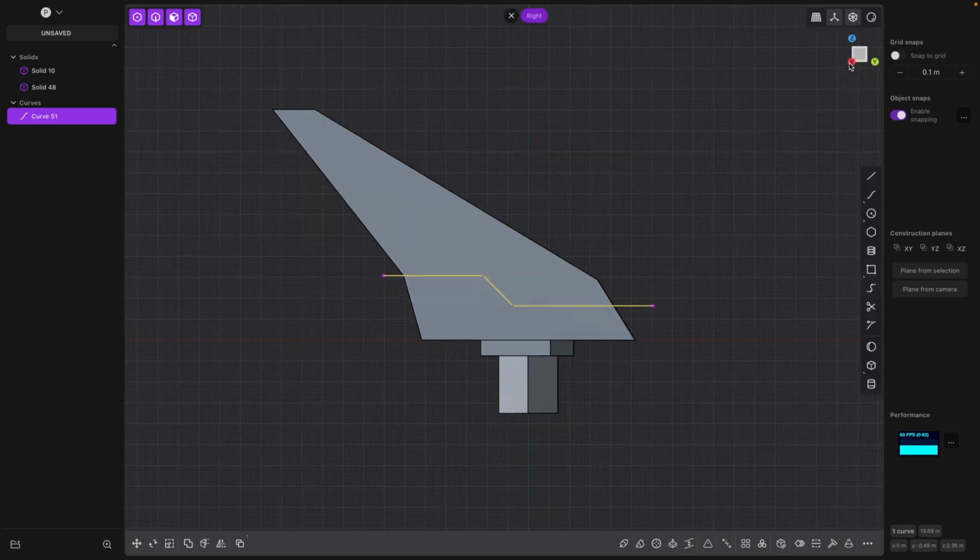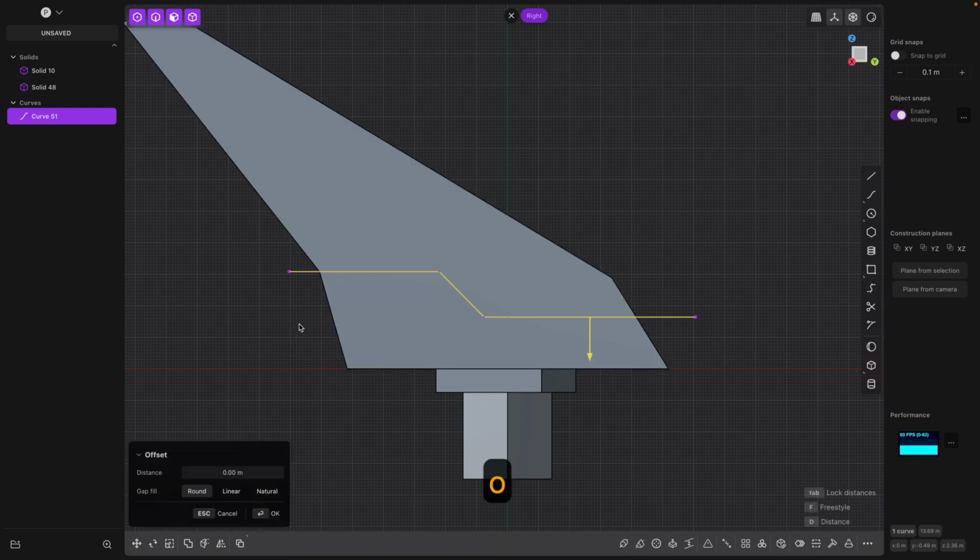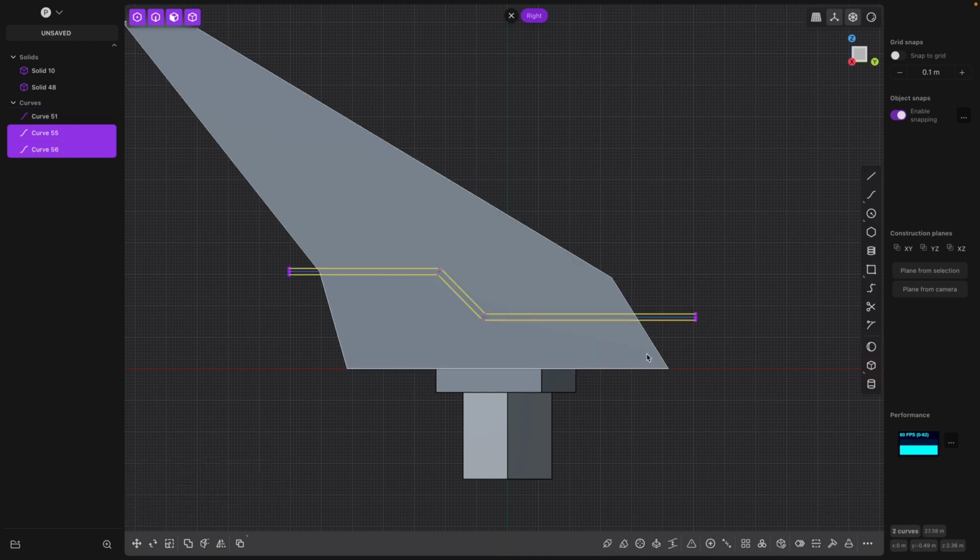So if we're going to imagine dragging a panel line chisel along this line, that's the line we want to create. And I want to pretend that we're dragging a 0.2 millimeter scribing chisel along there. And so I want a 0.2 millimeter wide line. So to do that, I'm going to offset this curve, and I'm going to pull this down. I'm going to hit tab again, which allows us to offset in both directions. And if I enter an exact value here of 0.1, then I've gone 0.1 millimeters away from the line below and also above. So I end up with a 0.2 millimeter wide line.